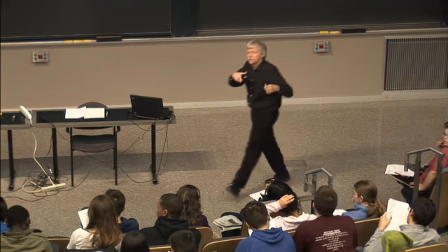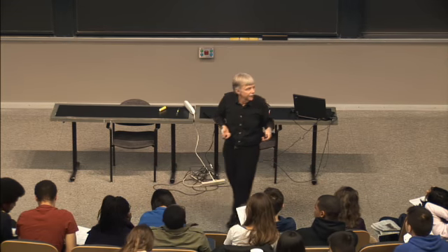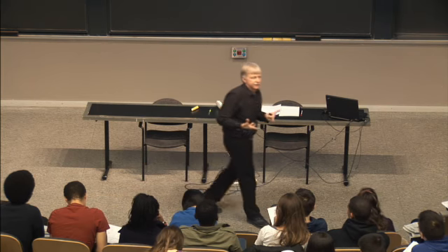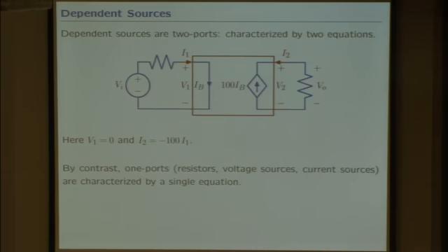So the point is, these are a different kind of element, controlled sources, dependent sources, but they're not too hard to work with. They look different structurally. So think about what's going on here. The current-controlled current source, I have to think of that as a box because the current source has to know the value of IB. So somehow, this box knows about IB and it knows about the current source. They're somehow linked, so that's why I put a box around it.